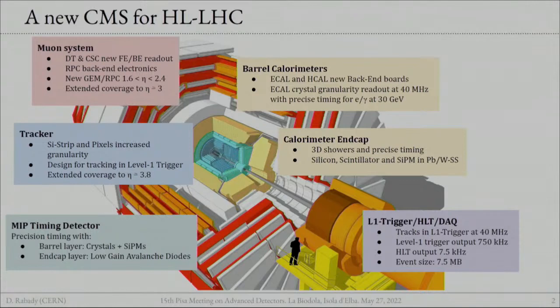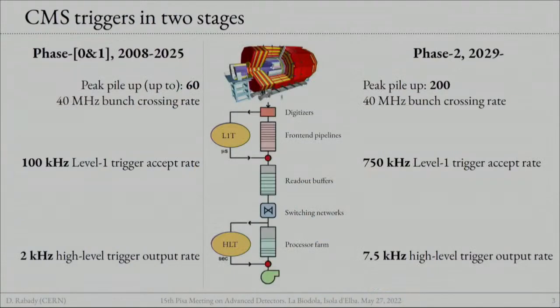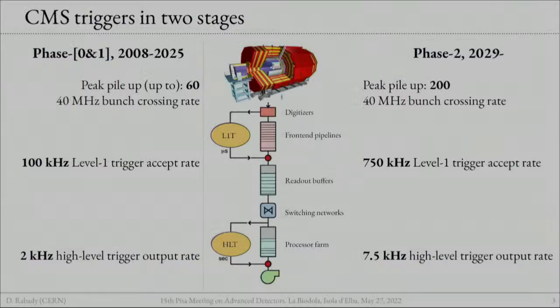I work at CERN, and I'm going to talk about the 14 megahertz level 1 trigger scouting system that we want to deploy through the CMS phase 2 upgrade. Very briefly, CMS is undergoing a big upgrade for the High-Lumi LHC. From the trigger side, this means we'll get new trigger primitives from the muon system and from the calorimeters. And for the first time ever, we'll have trigger primitives also from the tracker. So we'll have tracker tracks at the hardware trigger.